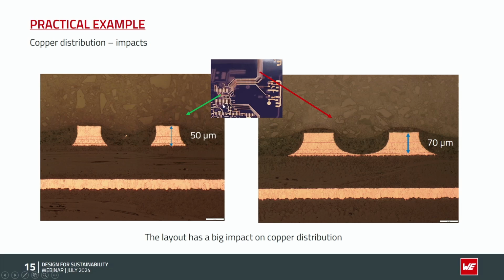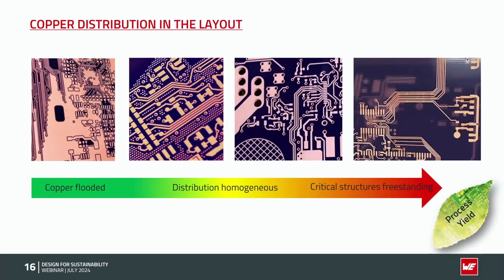Here, only a few millimeters away, you have these tracks which have no copper around. So all the galvanic plating was added to these lines, and in the same board we have 20 microns more on the surface. The etching was optimized to the 50 micron and was not enough here. So we have a short, the board is a failure, and you have a low yield. What can you do against such a thing?